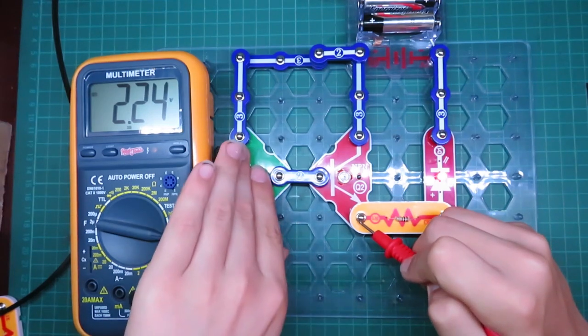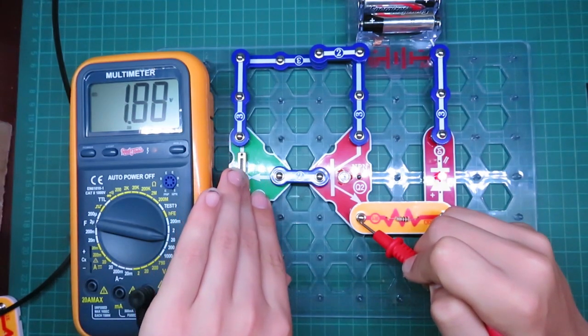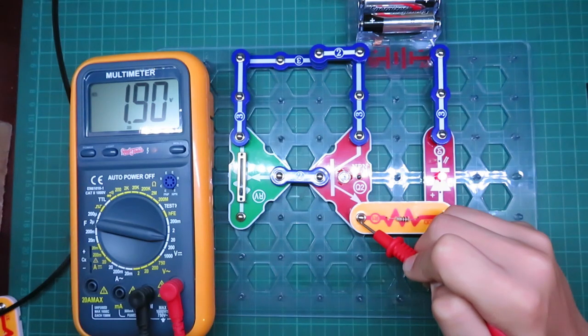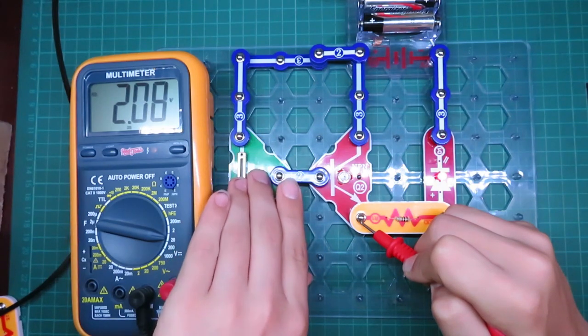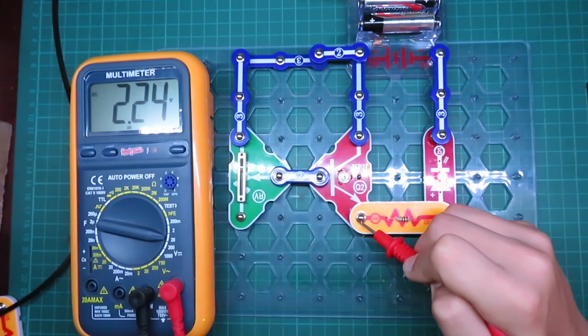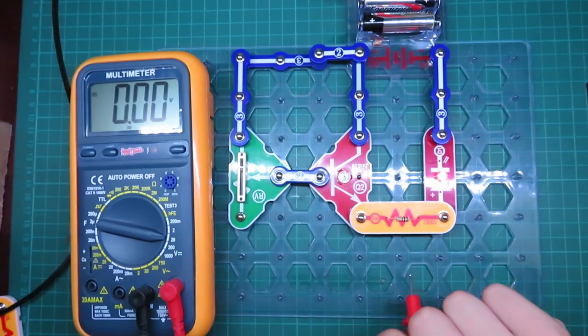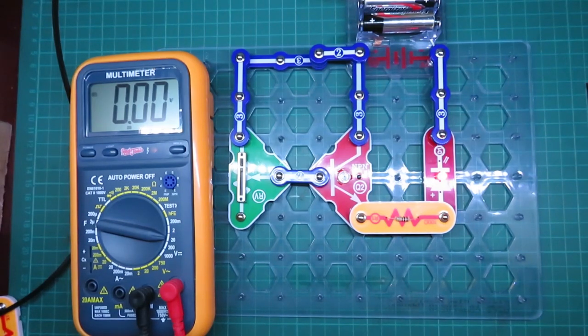And if we adjust the voltage down, you can see we go all the way down to 1.9, it looks like. So if you were to use a bigger potentiometer, you could probably have a greater range right there, but that's using the transistor as a potentiometer. Now let's try using the transistor as an amplifier. We'll have to turn on the oscilloscope for this one.